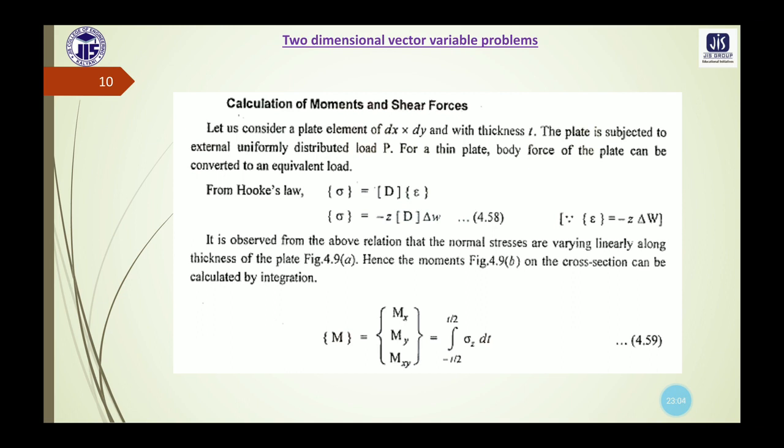The plate is subjected to an external uniformly distributed load P, and for a thin plate, the body force of the plate can be converted to an equivalent load. Now from Hooke's law, we can write that sigma vector, that is the stress, equals D matrix multiplied by the strain matrix.